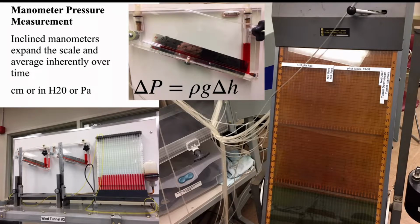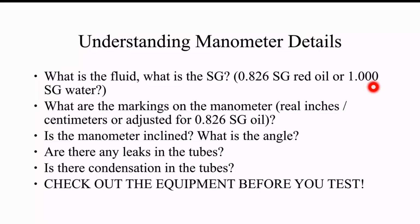There's not much complicated about these manometers, but you do have to check up on the practical physical details. Make sure you know what fluid you're looking at, what the specific gravity of the fluid is, whether you're working with water or with the lower specific gravity red oil. And what are the markings on the manometer scale? Are they inches or centimeters? Are they adjusted for the incline? Are they adjusted for the specific gravity of the oil? Make sure you know what you're measuring